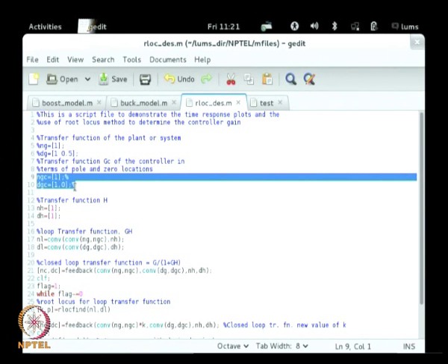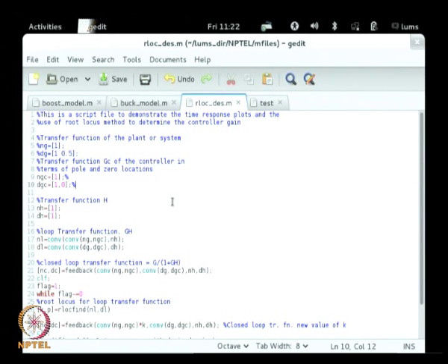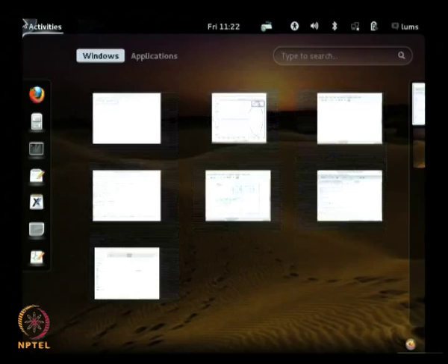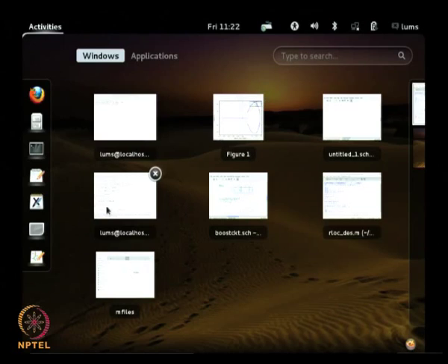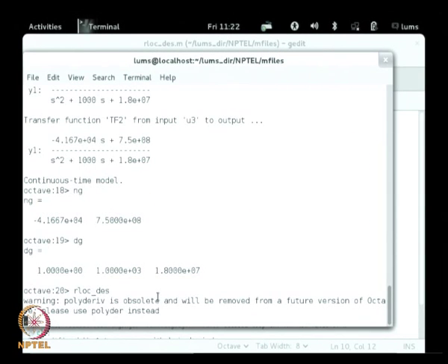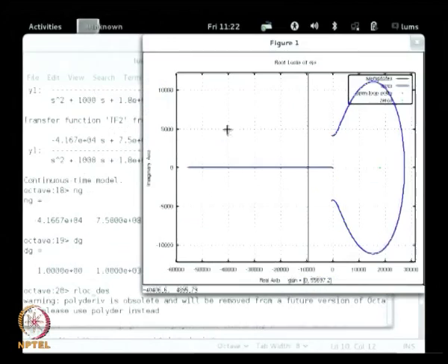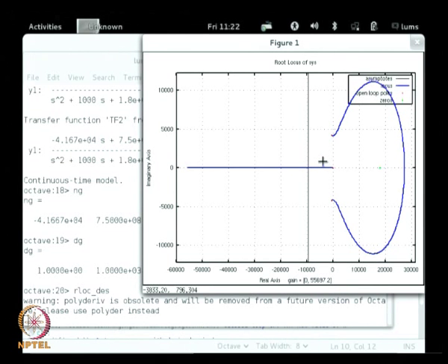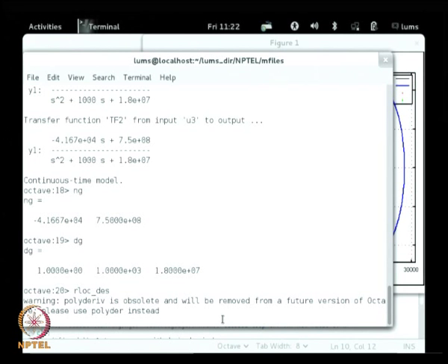Of course, you can make the control structure P, PI, or PID later on, but the concept is to propose that. Then we get a root locus plot generated by the tool, and we need to specify the closed loop location.